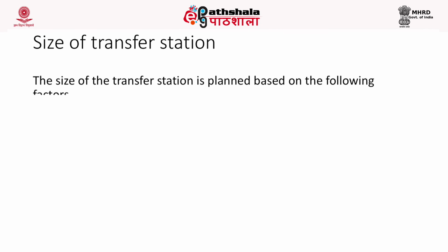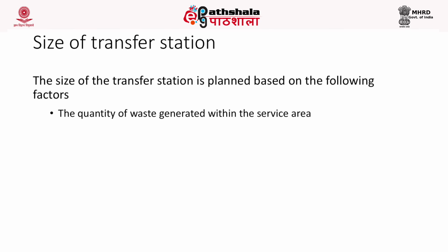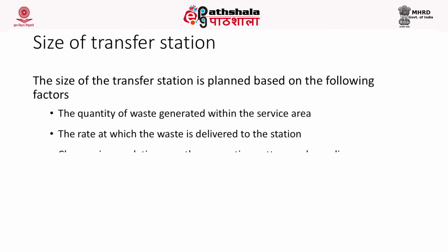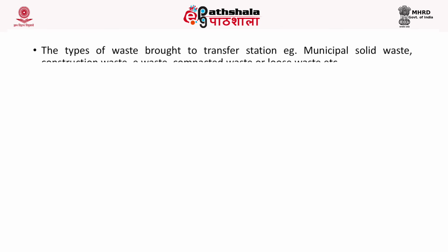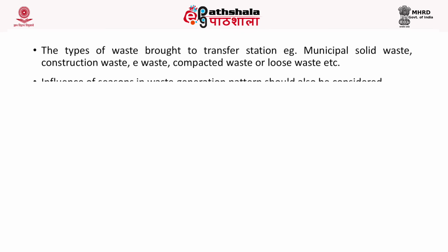Now, let's discuss the size of the transfer station. The size of the transfer station is planned based on a few factors. They include the quantity of waste generated within the service area, the rate at which the waste is to be delivered, changes in the population growth, segregation pattern, recycling programs, the peak flows of waste, and the types of vehicles delivering the waste. The types of waste brought to the transfer station, that is the municipal waste or construction waste, e-waste, compacted waste, or any other type of waste.